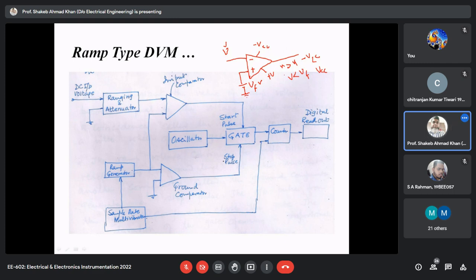So this is a very simple piece of hardware that suits very well when we are interested in converting certain voltage levels into a switching signal, or a one bit binary signal. This you must have studied, and this is the way it works and how it is used. Right now the output is in the form of bipolar binary, meaning minus VCC or plus VCC.